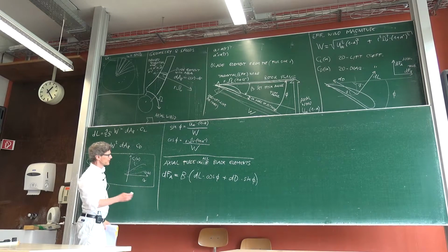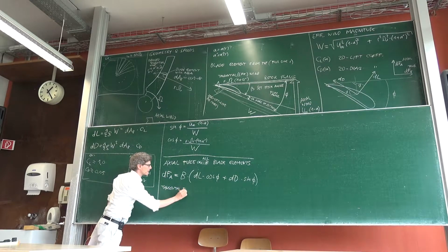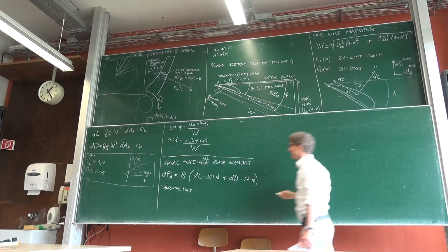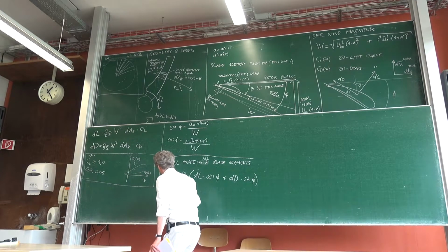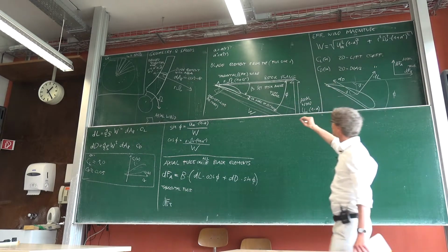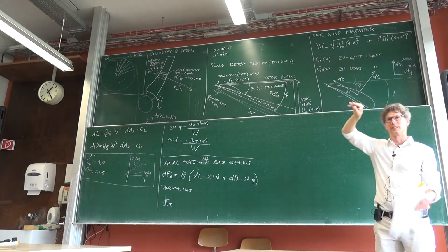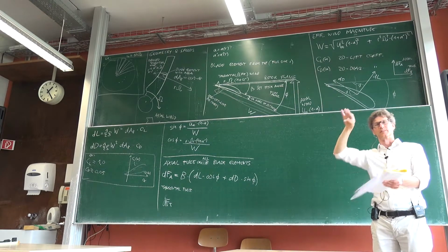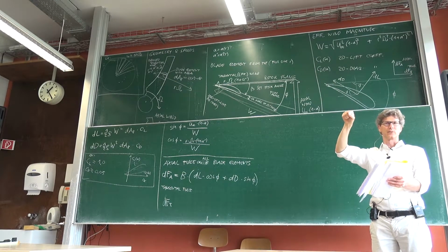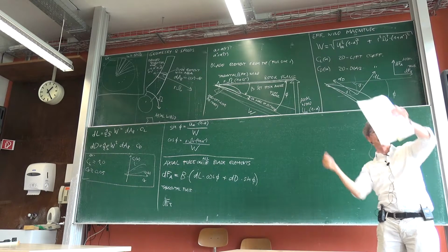So the other force is the tangential force. And I should say that this tangential force is this dFT, right? But please keep in mind, in reality, it's not just a force. In reality, because it's an annulus, this whole thing is a ring, right? The picture with the ring is already gone. But the tangential force is actually rotating the flow. It's still a force that I can interpret, but I could also translate it to a torque if I multiply this force with the radius. Then in reality, it's a torque, so to say.